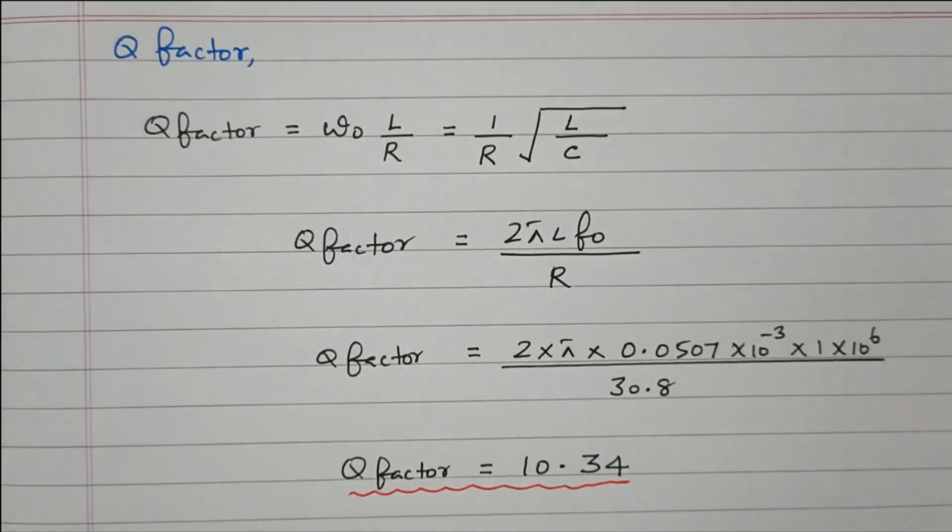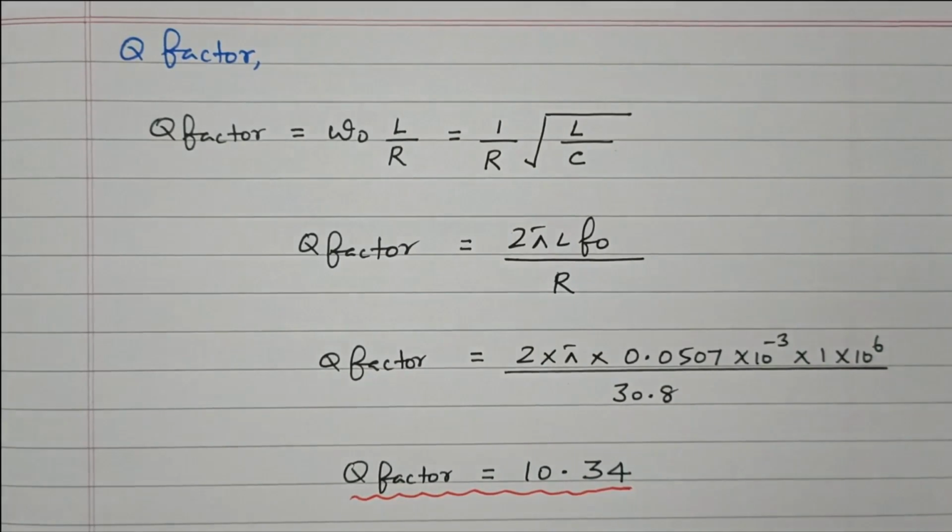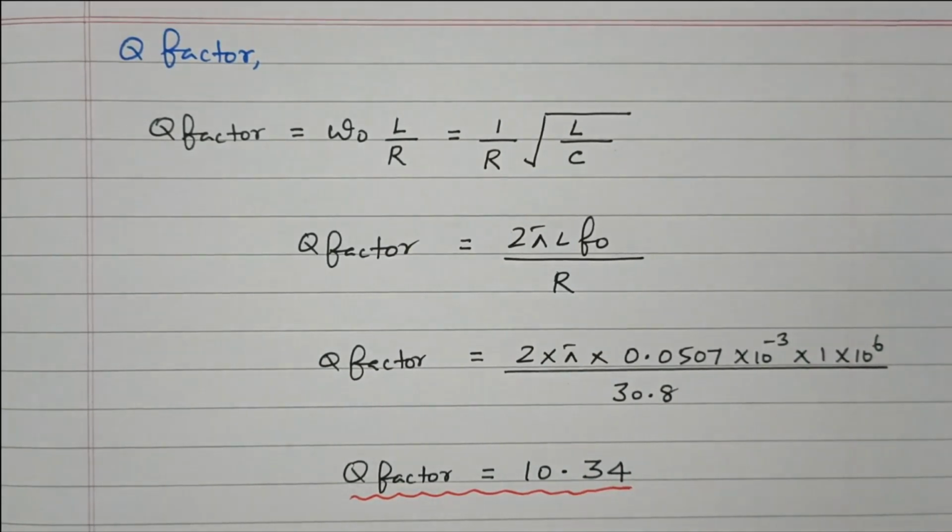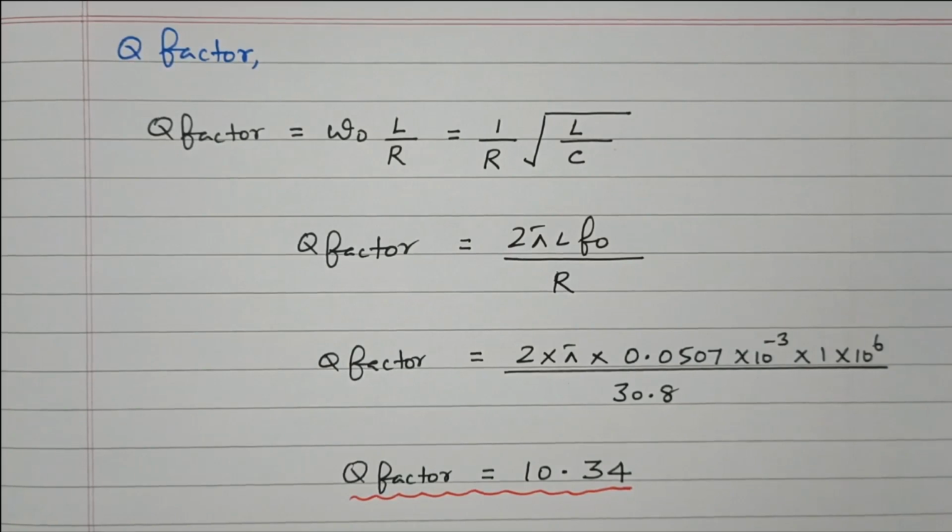So in this problem, we discussed the capacitor. The capacitor value is changed from 500 picofarad to 600. At that time, the current becomes half of the value. In this, we got Z equal to 2R. At resonance condition, only the resistance will be available, so that is nothing but Z equal to 2R. From that, we calculated the XL, XC values and the R value. Finally, we calculated the quality factor of the coil.